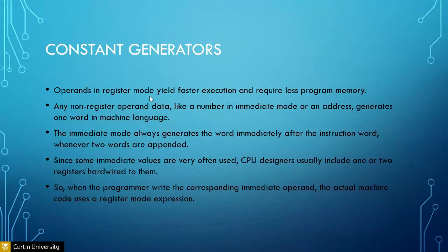If you keep on using immediate mode to get this number 2, you will waste a lot of programming cycles. What you can do is extract these constants 2, 4, 1, 2, 4, 8 from the status registers. We're going to show how to do it, but for this lecture, just accept it at this level.